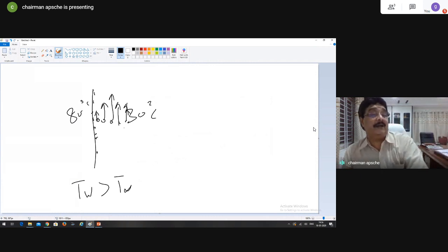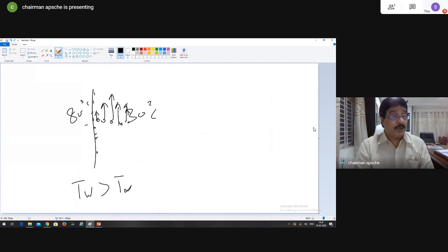If you go further, this molecule's temperature will not be very high because it is far away from the plate. Though the frictional and inertial effects are not felt here, the buoyancy force is less. The very driving force is less because it is away from the plate. Where it was 70 degrees centigrade, it is now 50 degrees centigrade. So a 50 degrees centigrade fluid molecule against 30 degrees centigrade, though buoyancy is there, the force is not much, and therefore it moves slowly.